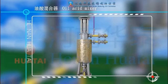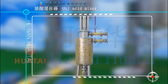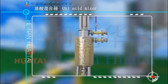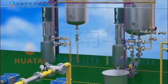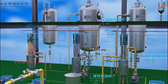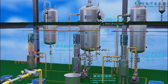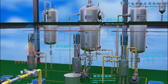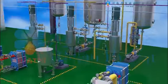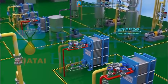Ratio-metered phosphoric acid is intensively mixed with the oil inside the mixer. The acid refining oil goes into the acidification tank for a delayed acid refining reaction. After the reaction, the oil goes into the lye mixer and is intensively mixed with ratio-metered alkali liquid. The mixed oil goes into the alkali refining reaction tank for a delayed reaction.